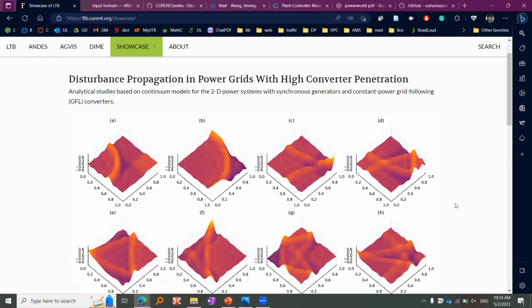It's going to take a while for that to move across, and it varies on the loading, the inertia you have in the system, and what the disturbance is, but it moves at anywhere from a few hundred miles per second to maybe 800-900 miles per second across the system. It kind of looks like a wave. In fact, this was first discovered on the West Coast by, well, I don't know if somebody before John Howard, but anyway, one of the engineers at BPA discovered this because you could see things move across, but it moves across slowly enough that you can sort of respond to it.